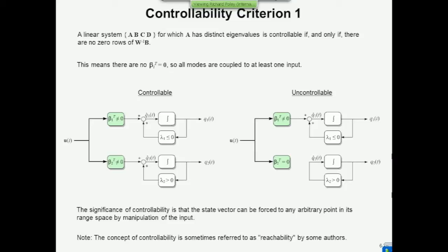See, this kind of thing may not be so obvious if you just have a random choice of state variables and a full state variable description, but it's obvious now that there is an unstable and uncontrollable mode present in the system, and that's going to lead to problems later. So if you have a modal decomposition, the classification between controllable and uncontrollable is very clear to you. You just look for non-zero beta I vectors. Now, that's the easy way of seeing things.